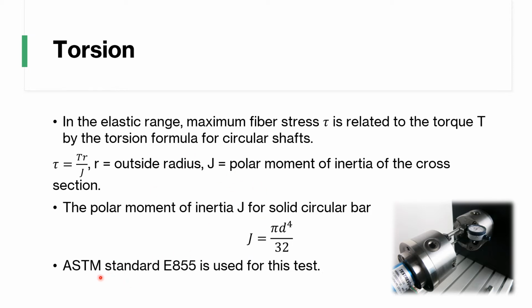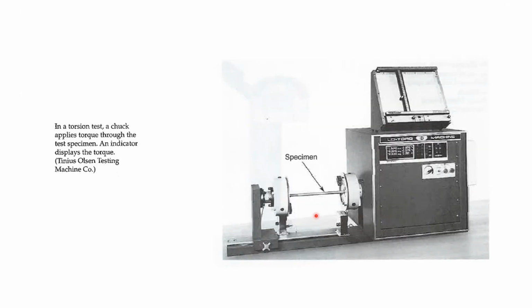Then we're going to follow the ASTM standard E855 for this. No need to remember anything. We are following a standard. So when you do this test, you know what to do. You have to follow a standard, so find it. They're going to give you the book or the application on your PC or whatever, and you're going to follow everything. Don't use different standards. Strictly follow that, and it's going to make your life easier.